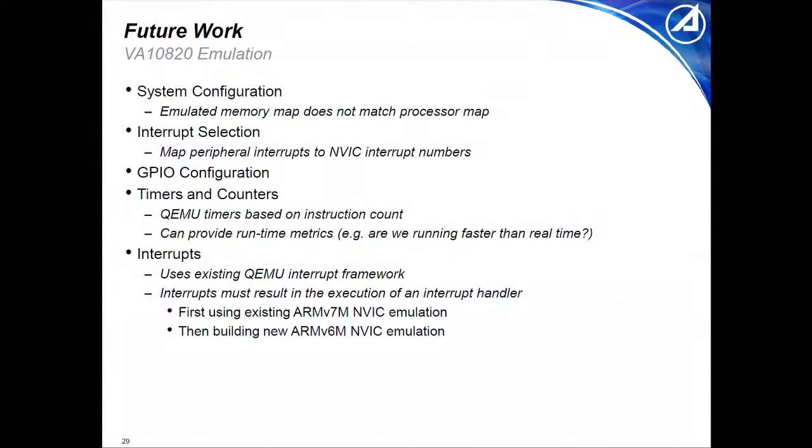We're running bare metal with no operating system, so we have a big event loop timed off of some periodic, I think, 10 hertz timer. We weren't able to emulate that, so we had to tweak the existing flight software a little bit.